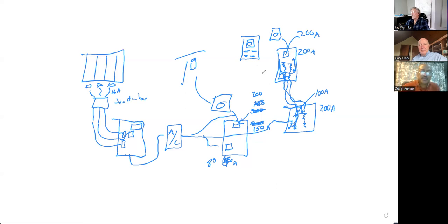But where it's going to cause something tricky is, let's say you've got this main disconnect out here, and now you're coming in and connecting into a main here. We're all going to still think that's our main, but it's not. This is the main. So now we have to keep everything separated here and not bond those things together, because they're bonded out here.